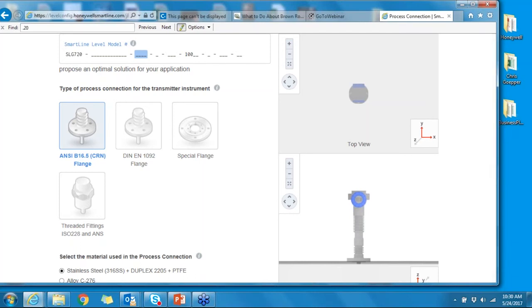The electrical was already run up to the top of the tank, and this was a 40-foot terminal tank. And so we hauled all the hardware up there, and I believe our hardware, the flange, was a standard ANSI flange. I think it was 3-inch, 150-pound flange, and the one that was on the tank was, I believe, 4-inch.